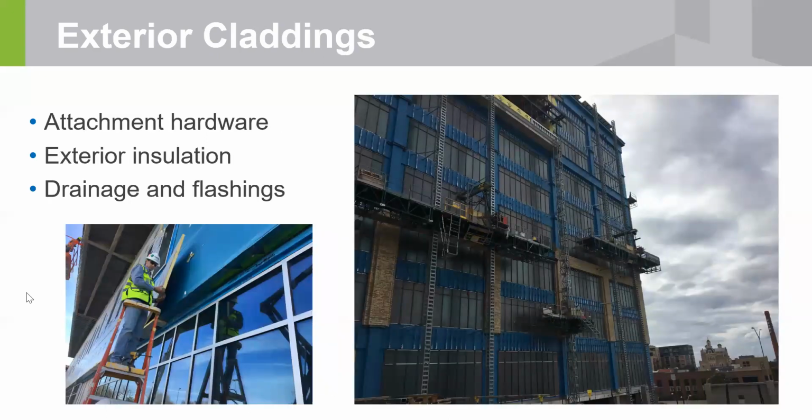Okay, progressing through the work. Now here's the overburden. I mentioned before that this is your primary air barrier, and once it gets built into the wall assembly and covered up, it's going to be really hard to do anything about it if you don't like the results. So inspecting everything visually for continuity and for compliance with the details is very important. You can see a guy test fitting a piece of rigid polyiso foam board that was on part of the project. Most of it had the mineral wool semi-rigid bats, as shown in the photograph on the right. You can't see it because the bricks are up already, but it goes between those silver rails.